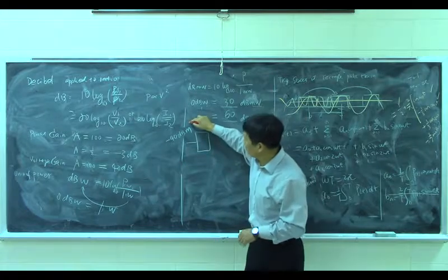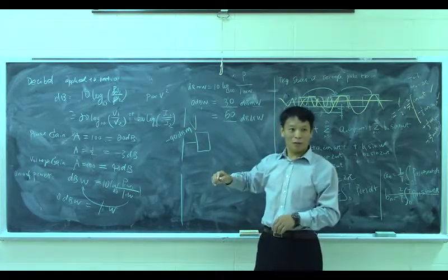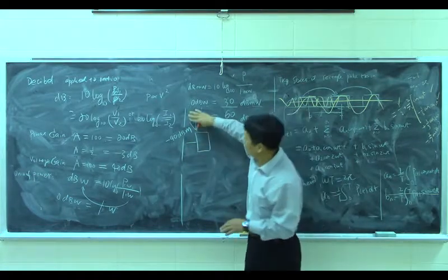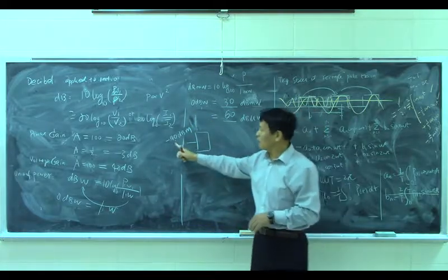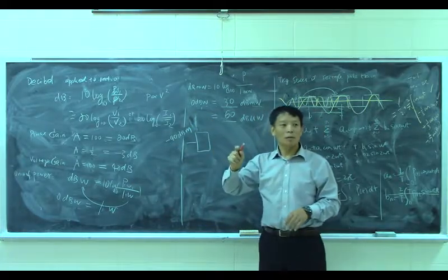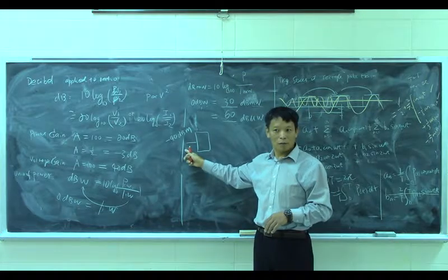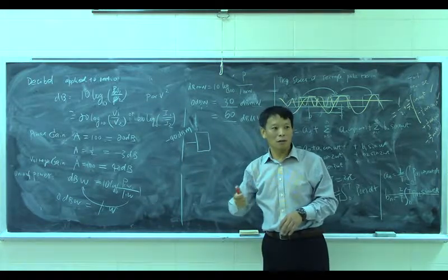If you mean dB voltage, then you need to write that out. Only for power can you ignore this. So that means negative 40 dB milliwatt. That's the input power from the cable company to your home.